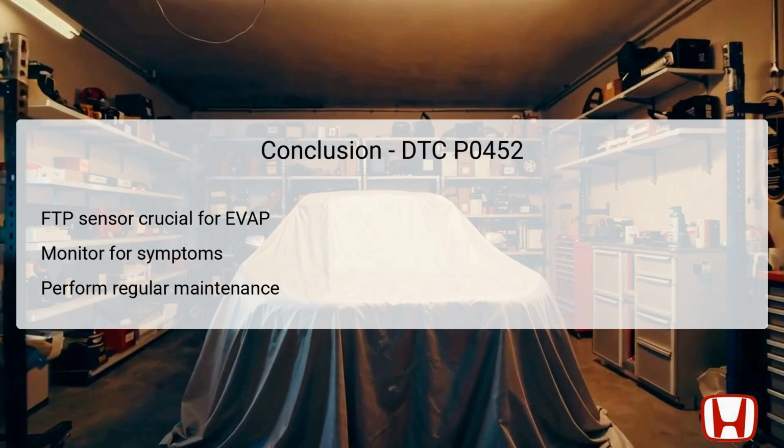In summary, the DTC P0452 signifies an important issue regarding the fuel tank pressure sensor circuit for the Honda Accord models 2012 to 2017. The accurate functioning of this sensor is paramount to maintaining proper evaporative emission controls and ensuring environmental compliance. Symptoms such as a check engine light, reduced fuel efficiency, and failures during emissions tests should prompt immediate attention.